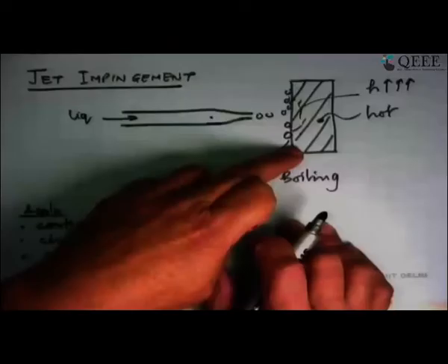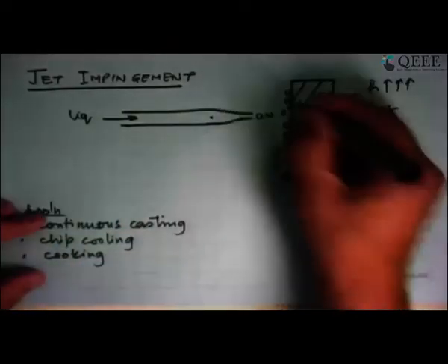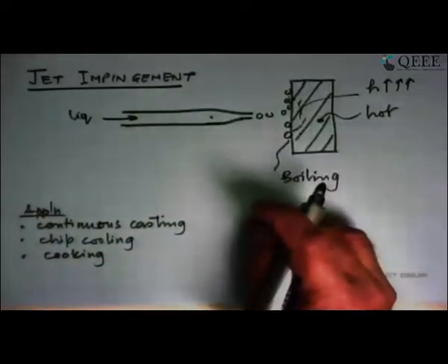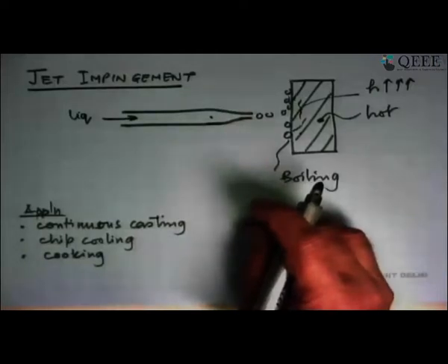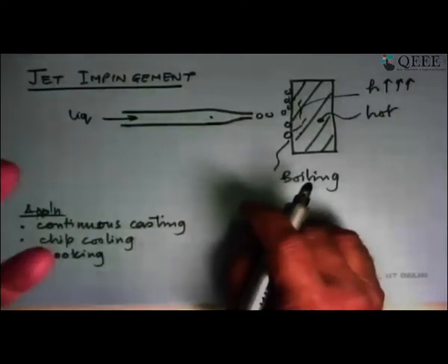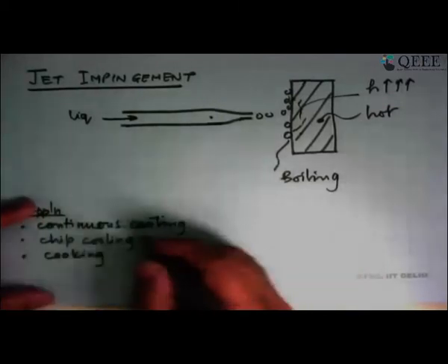Such ideas have been used for cooling chips, where locally you want to do a cooling, and with a small little jet you keep pumping on it drops of saturated liquid, it boils, cools it very fast, and your temperatures come down. So that is one example of chip cooling.